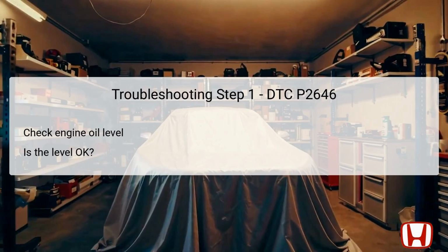If the oil level is acceptable, this suggests that the oil issue is not the source of the DTC, indicating the need to move to the next diagnostic step. Accurately performing this task helps eliminate one of the most common causes behind the error code.